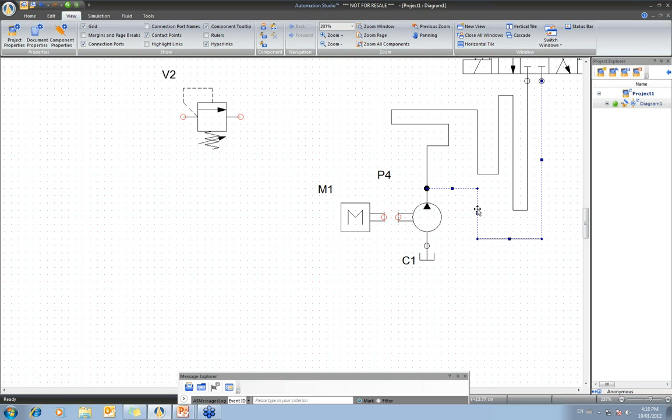It might look a little bit messy here, but I wanted to show you that once the line is created, you can also click on the line. This activates what we call the grips, small handles almost everywhere on the line. By taking these grips, you can move the line. If you take a vertical grip, you can move left to right; with a horizontal grip, you can move top to bottom; and when you pick a corner, you can move in both directions.